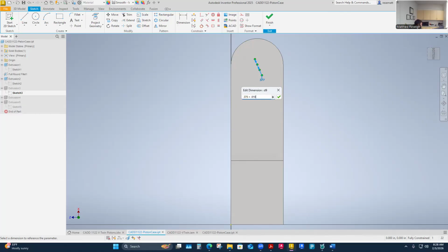As I go to use my printer, or our printer here, it's probably for hole to shaft, like for bolts and stuff. I'll remember that, 10 thousandths is probably the best tolerance, at least with this ABS plastic that I'm printing right now. When I Googled it, this is the difference of Google to a machine. It doesn't know what machine I have or necessarily what my material is. It's just giving me kind of a ballpark. That was my 0.0008, and it was way too small. I needed much more than that. For some printers, that might have been good, but not for mine.